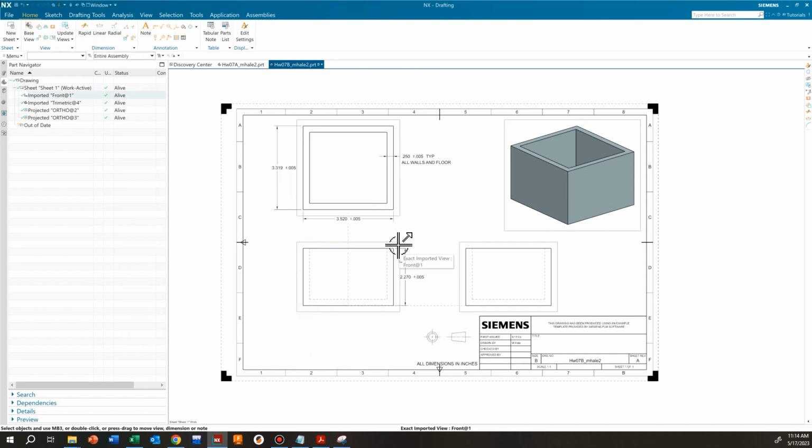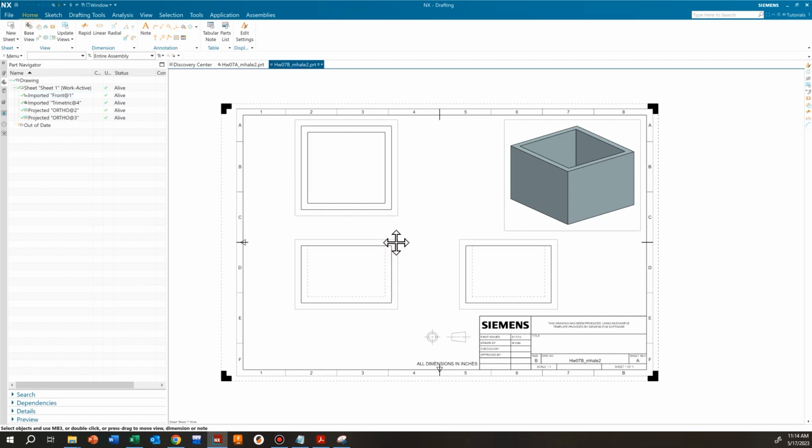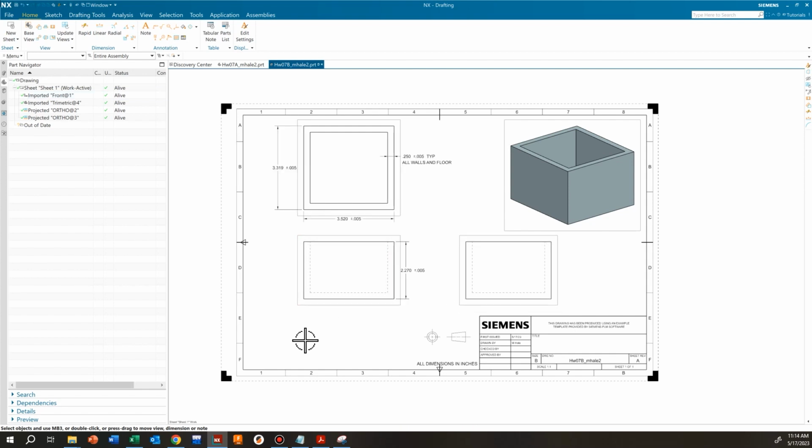So a few more things that we need to take care of is that we need to specify the material that we're going to be using. We're going to add a title over here. And then also we need to make a note to the manufacturer for the size of the box, or the size of the cylinders that the box is for. Just puts more information for the specific sized box. And we can add that information by making notes.